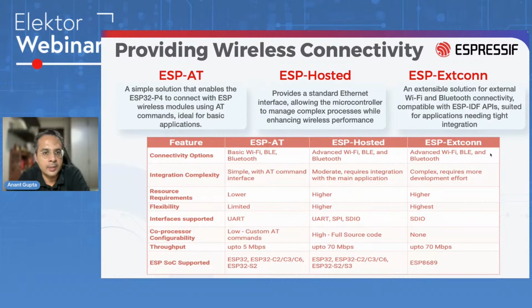It requires some integration effort, but if you are used to running ESP with wireless capability, you can call the same APIs as you would have called on other ESP32 or ESP32-S3 or other Espressif products, and ESP-Hosted on the ESP32-P4 can manage to call those APIs in the background in the hosted mode.